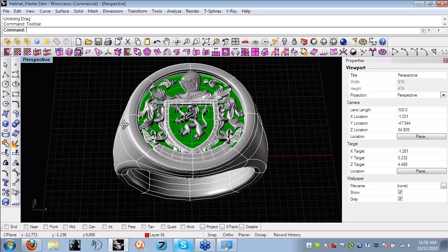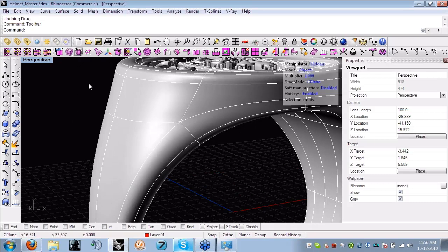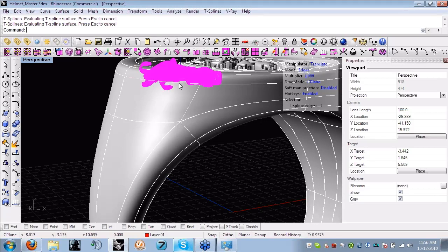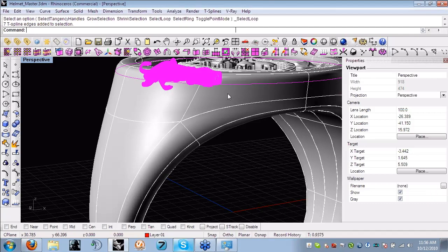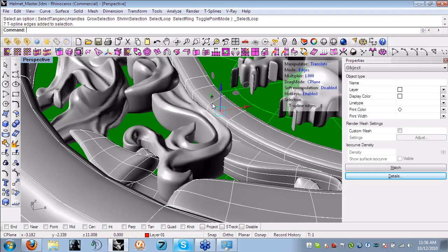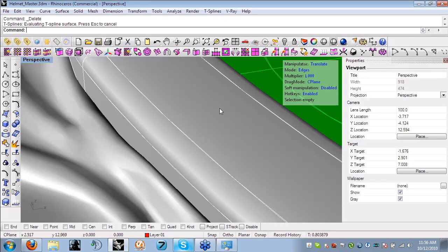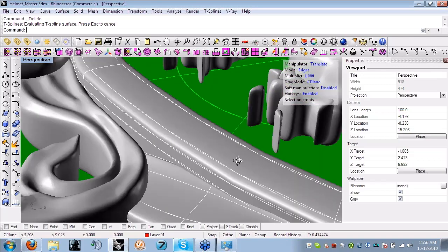Yeah, at any point, obviously if you get too heavy, it's going to get challenging, but you can come in here and select edges and faces, especially edges. If you find that there's an edge ring that you don't want any longer, you can simply select it and delete it and start removing that information from the T-spline, which of course is going to make some changes to the model, but obviously that's probably what you're after.